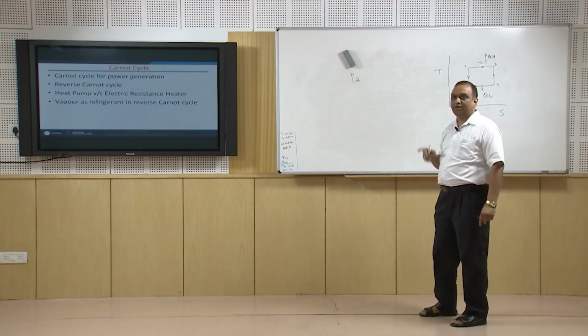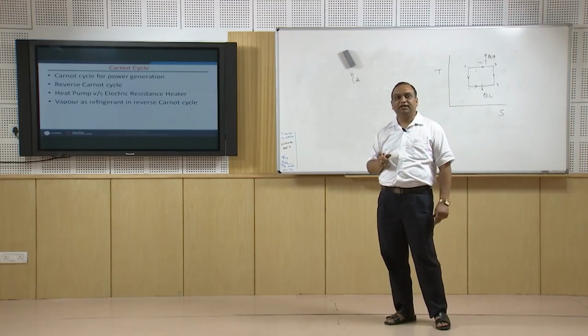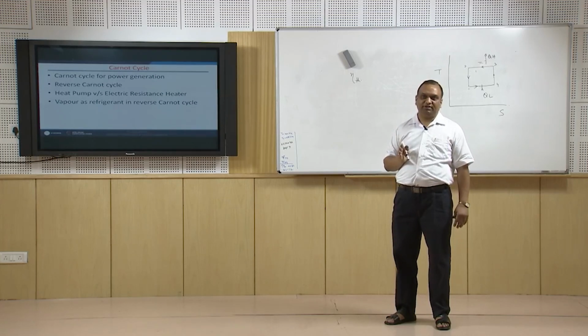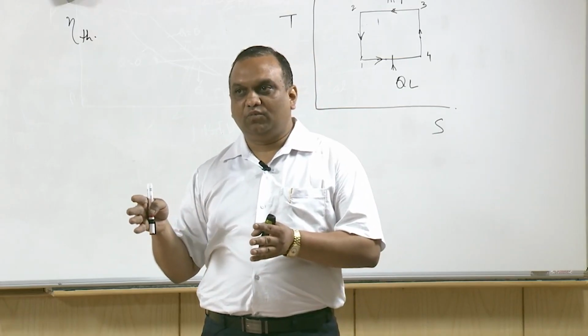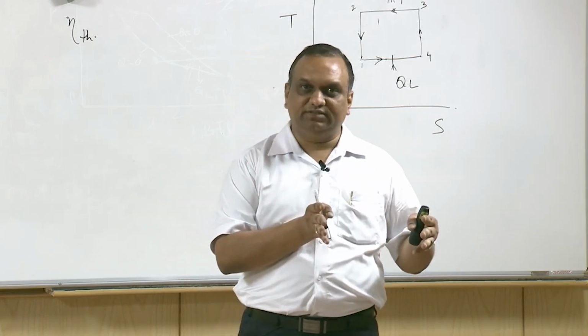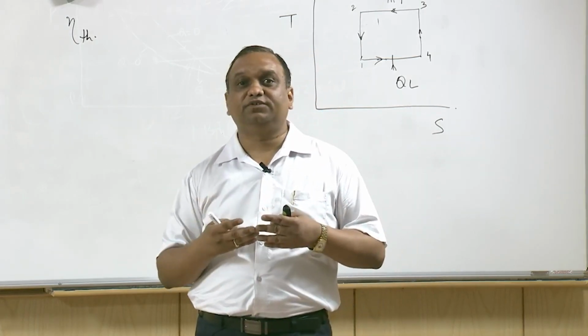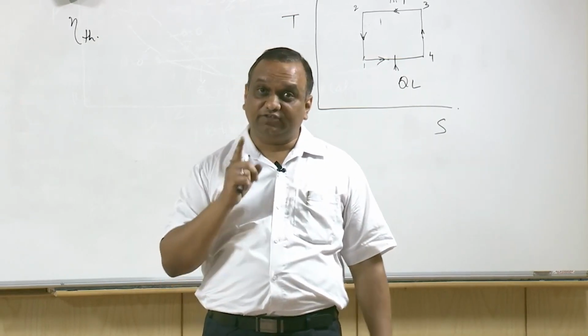So, for compressors, let us take an example of a compressor. If it is a reciprocating compressor and the efficiency is 65% or 70%, this is a poor efficiency, because in a compressor we are converting work to work, right? In this work-to-work interaction we are losing 30% or 35%. So the efficiency is low, and that too in a reciprocating compressor.